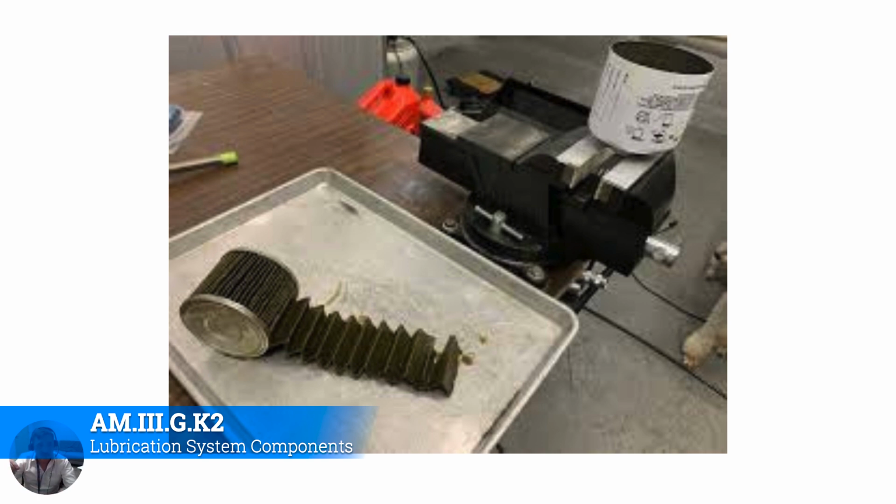As you pull it apart, you're going to end up seeing little shards of metal in there if the engine is falling apart. If you don't see anything, the engine's good. It's going to go back in service. So most of the time you don't find anything, but you always have to be really careful and look for it. Now, this guy's done a really good job.